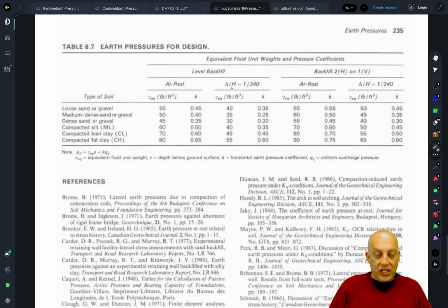But what they're acknowledging here is that clays will tend to creep over time and maybe go from an undrained to a drained condition and start pushing on the wall as consolidation happens or as swelling happens and the clay state changes. So if you are going to be supporting clay, you've got to be careful with shoring because it may change over time and go from basically zero pressure to something pretty high.